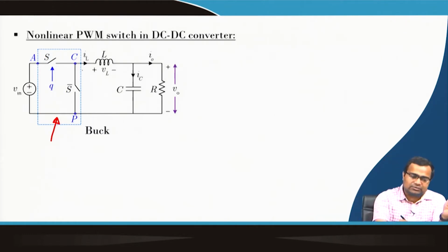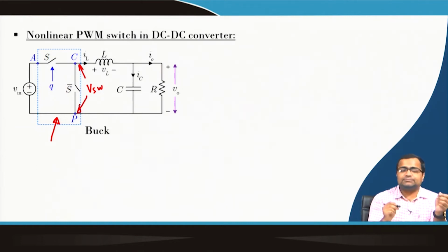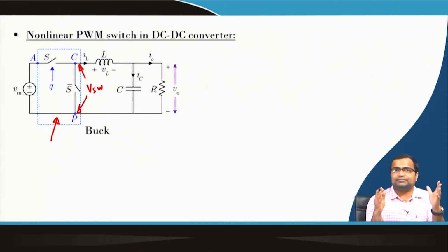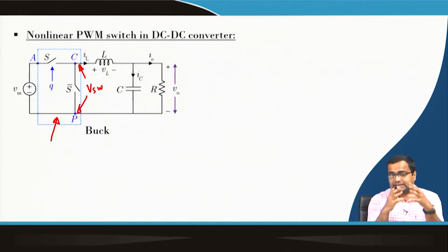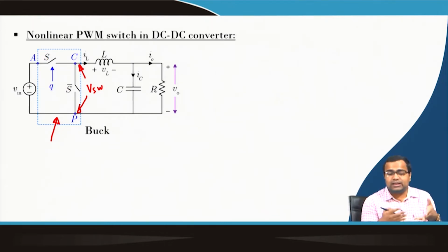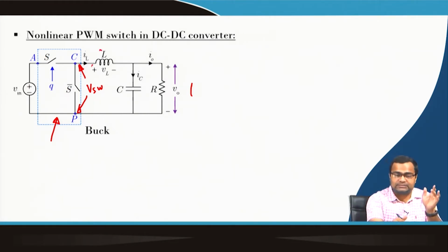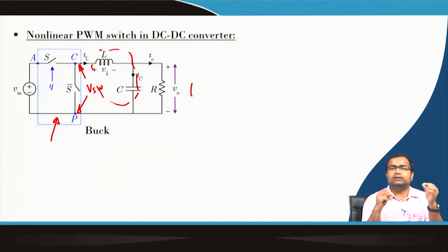Now, if we take the PWM switching converter, the block which is responsible is what we call the switch node voltage. This voltage changes like a pulse width modulated wave, and this will create an excitation for the RLC circuit. By controlling this switch node voltage, we can control the output voltage in the average sense, and it will also generate harmonic terms. If we design this filter element properly, the components associated with the harmonics and switching can be substantially reduced compared to the average value.